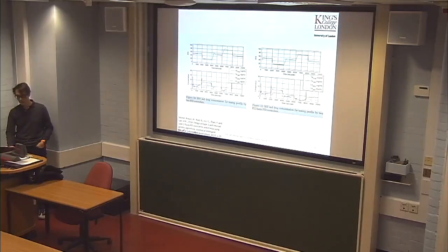To the left is the result using the two PID controllers. When we talk about the two PID controllers, it means that we are using two linear PID controllers, the traditional method, and then to the right, we're using the two interval type 2 fuzzy PID controllers. Referring to this diagram, we have the green line right here. It is a kind of tracking control. The blue line is the base value, that is the 52, the value we would like to control. As I mentioned, we would like to pull this line into the green region. This is the ideal trajectory we would like the blue line to follow, and then we are going to use the controller to draw the line into this green region.